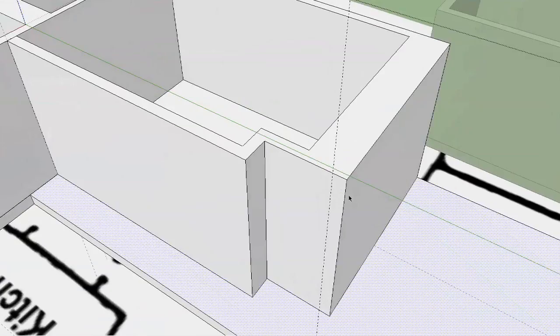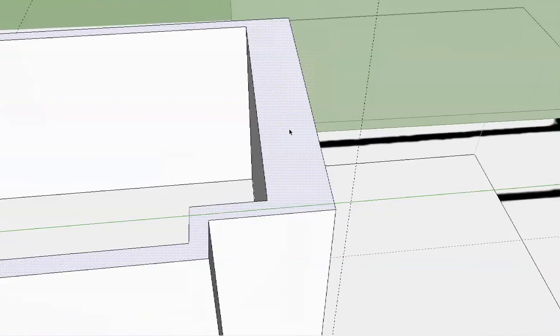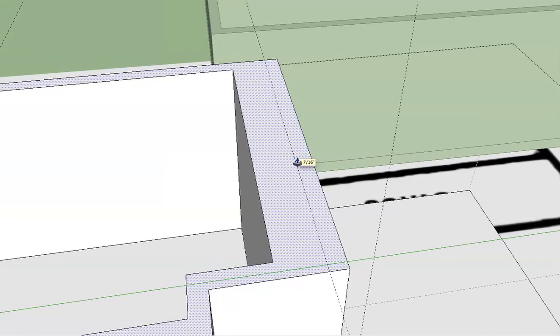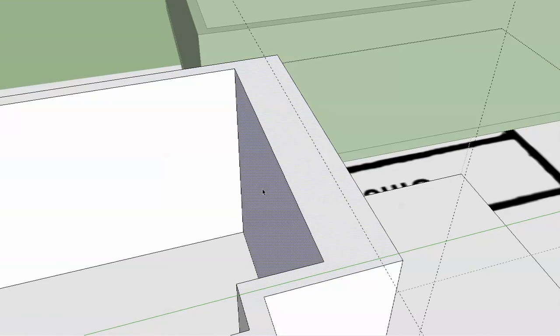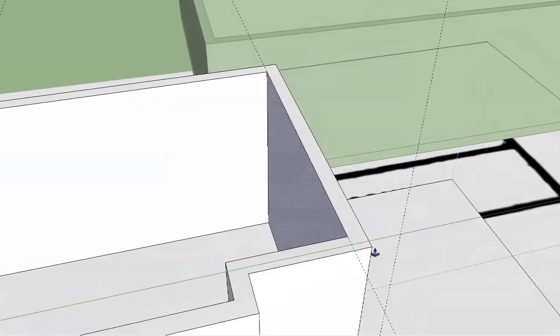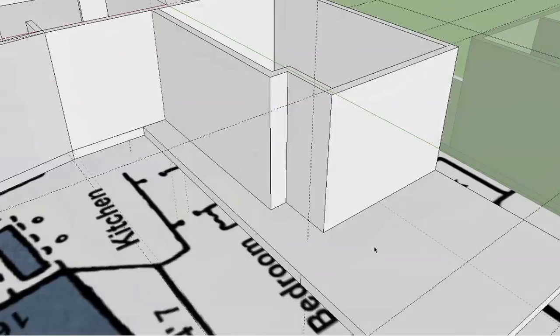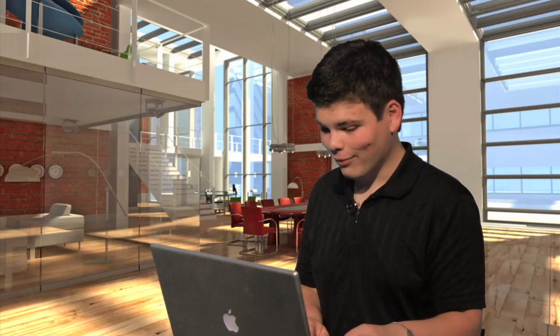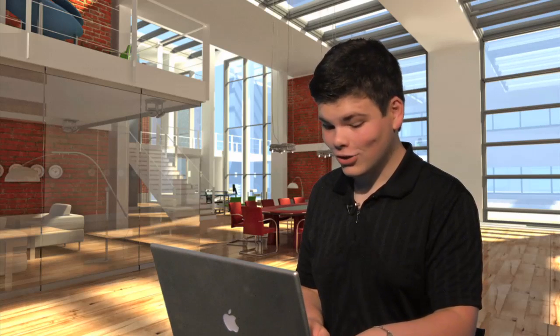So that's looking good. Now we've got this exterior wall very thick right now, so I'm going to go ahead and take another guideline in 6 inches and push this chunk of the wall back like this. Good. And there we go. That's what it should look like. That's the correct dimension for that room. So we made some pretty big changes, actually.